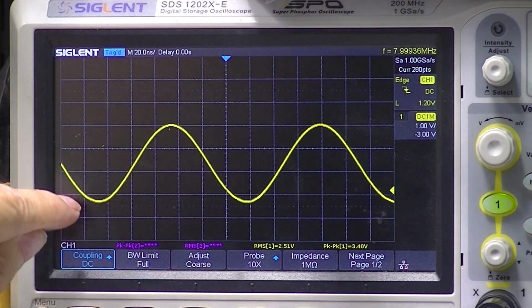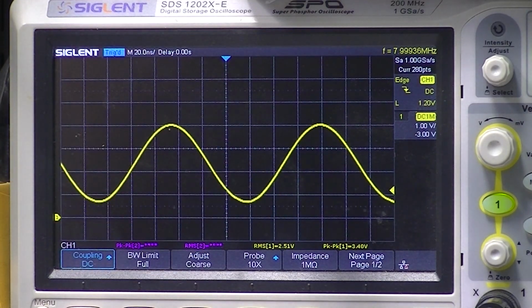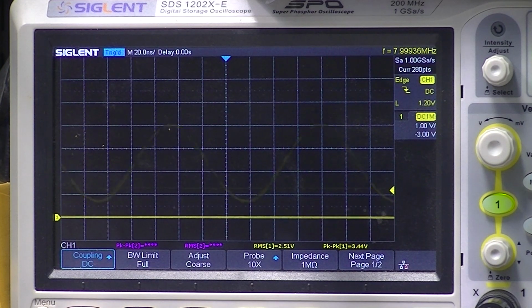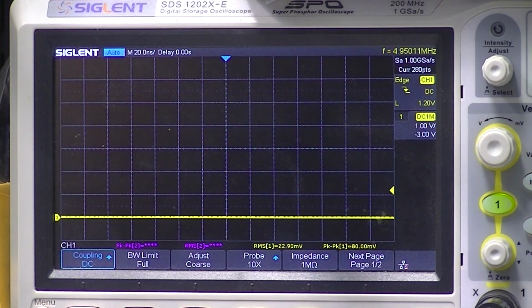But you see it never goes below 0. It's a sine wave that's above 0. That's pin 21. Pin 22 has a sort of distorted sine wave, about the same thing, floating above 0. So I need to try to, I hope, duplicate that signal.